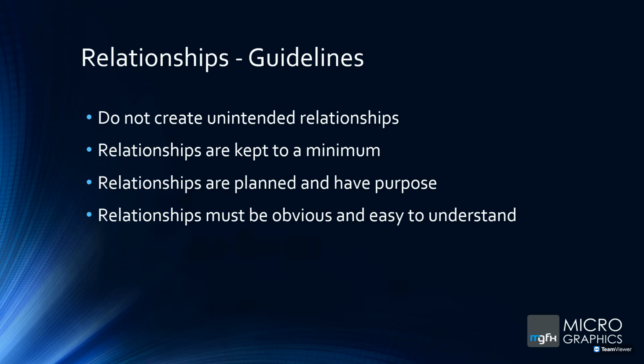Why are we doing this? Why are we putting in maybe a 90-degree dimension when maybe you could use a perpendicular constraint? Or if you put both in, why are you doing that? Just keep it to a minimum, plan it, and have purpose.